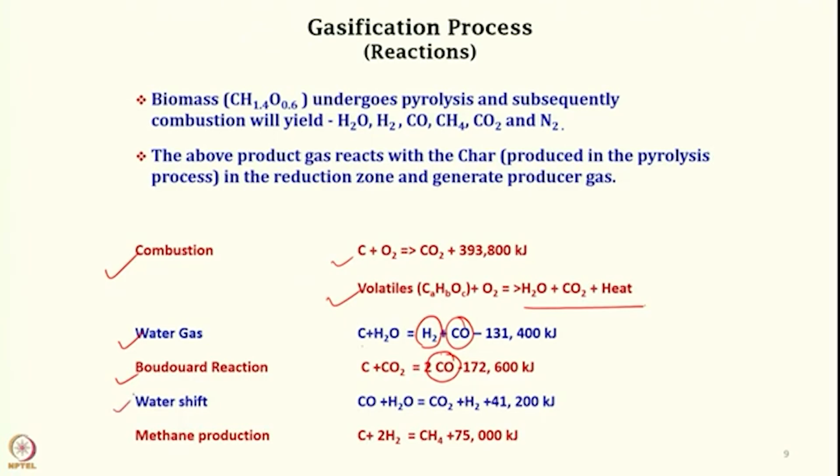Another reaction that I was talking about is the water shift reaction, where carbon monoxide also reacts with H2O. If H2O is present in the system, it will not only attack carbon, but also react with carbon monoxide, and this is a gas phase reaction. Gas phase reaction is again favored more compared to this solid gas reaction. So, this also gives you extra hydrogen, and when we want to enhance the hydrogen production, we can use this H2O to get more and more hydrogen.